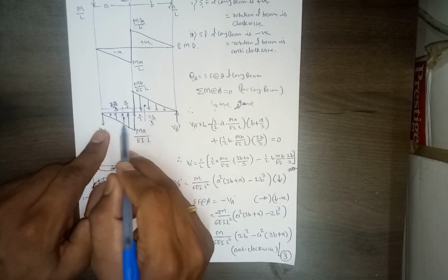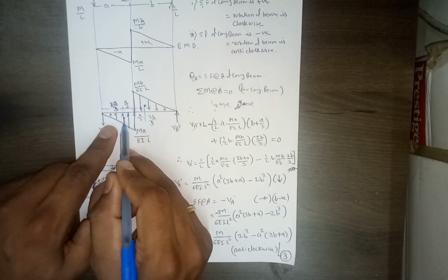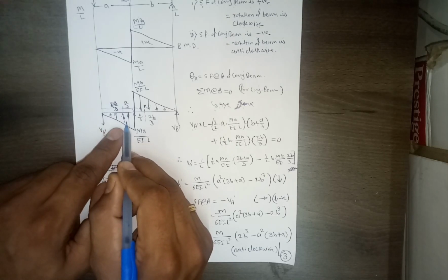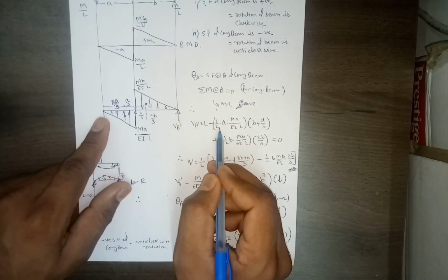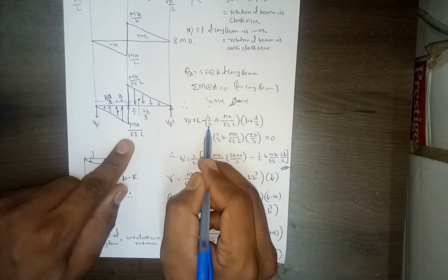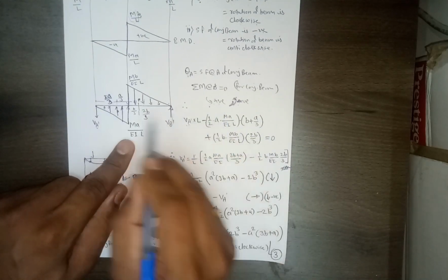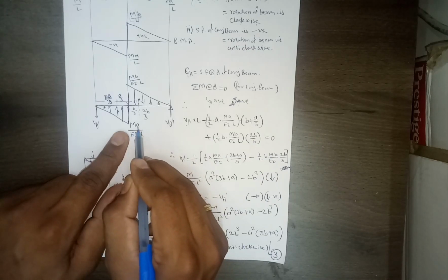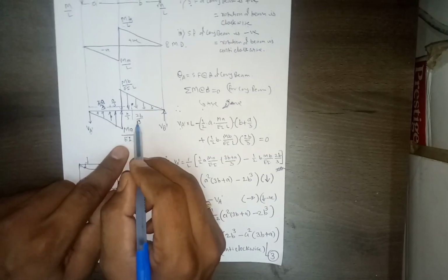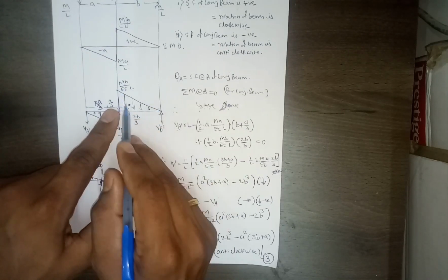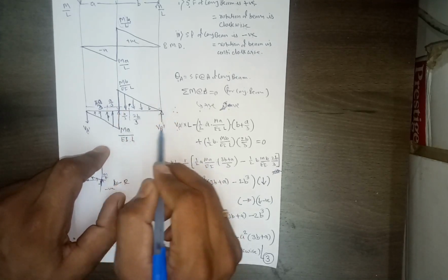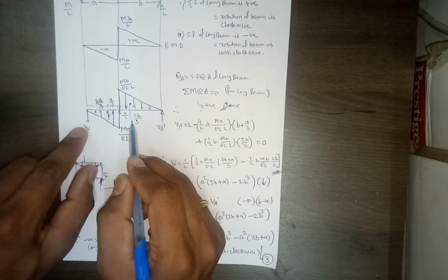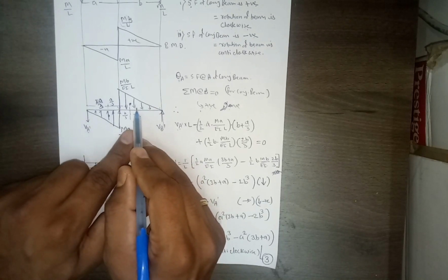So now we have to calculate moment due to this triangular portion. The area of this triangle will represent the total load. So load into distance. Load will be 1/2 base into height. This height is equal to MA by EI, right? And then this portion will again cause anti-clockwise moment like this reaction. So it will be positive.